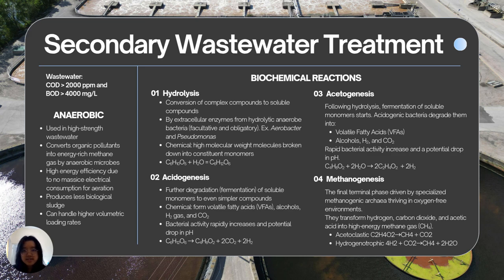First, hydrolysis itself is a conversion of complex compounds into soluble compounds. The conversion is done by extracellular enzymes from hydrolytic anaerobic bacteria, which can be facultative and obligatory anaerobic bacteria, for example, Aerobacter and Pseudomonas. From a chemical perspective, hydrolysis is a step where high molecular weight molecules are broken down into constituent monomers. The reaction shows the hydrolysis of polysaccharide, where it is hydrolyzed and becomes glucose.